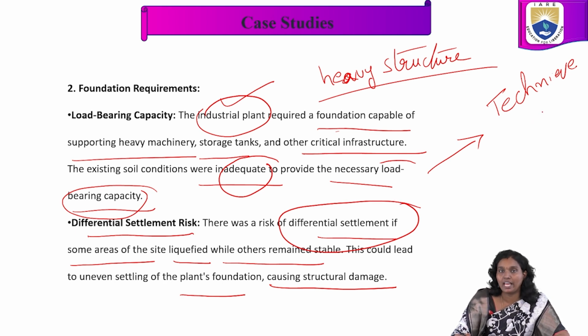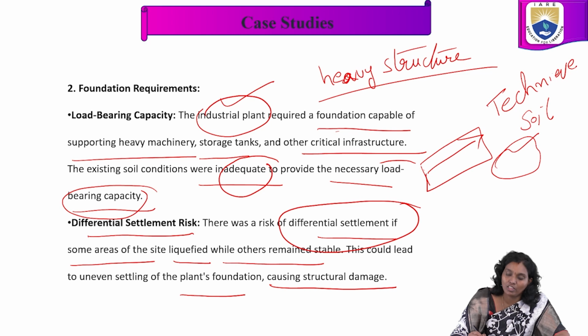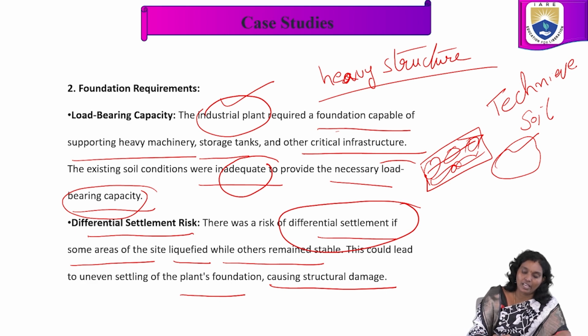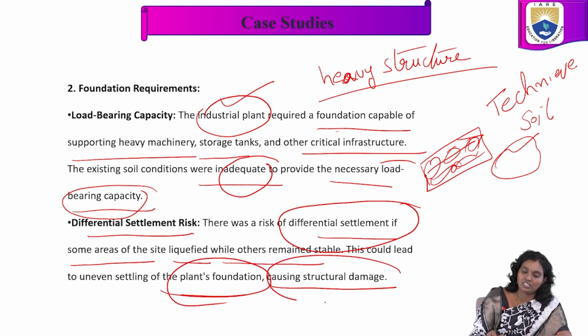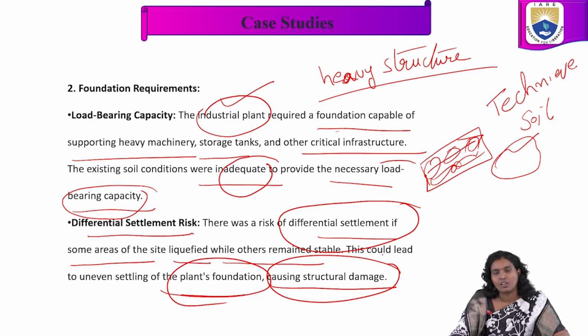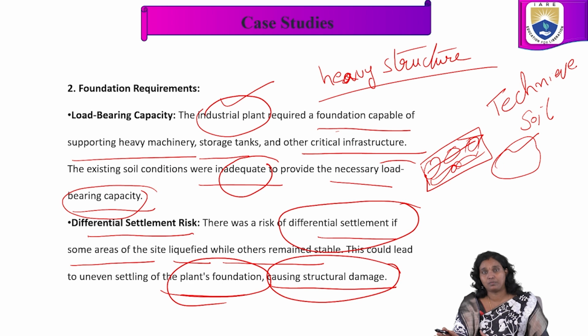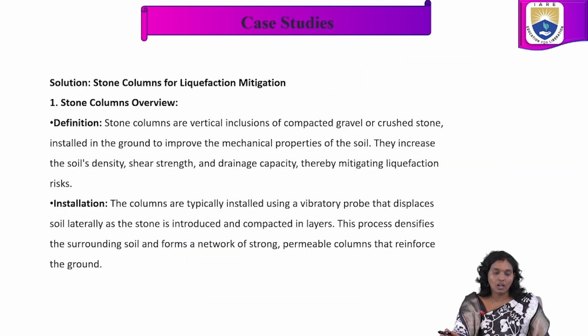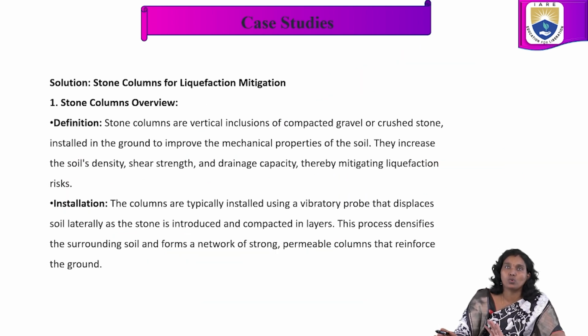So it is a different scenario. It depends upon the waves and the soil conditions. Whenever we consider the complete area, some areas may react differently because of the soil condition. Uneven settlement may affect the foundations, causing structural damage. Why? Because throughout the site, the soil conditions may not be the same. Some areas of the site may liquefy while others remain safe and stable.